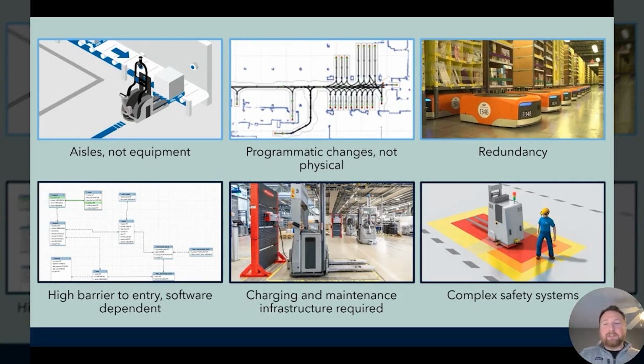On the downside to those, though, there is a higher barrier to entry on any AMR or AGV system. There's no equivalent of gravity conveyor or dumb accumulation for AMRs and AGVs. You are going to be likely very software dependent. Hopefully having a mature WMS at the very least in your building, likely a WES for execution, not to mention the fleet management system directly overseeing any of the robots.